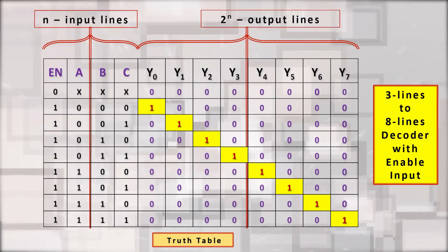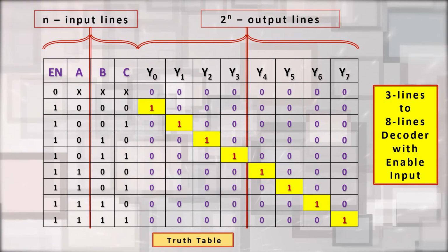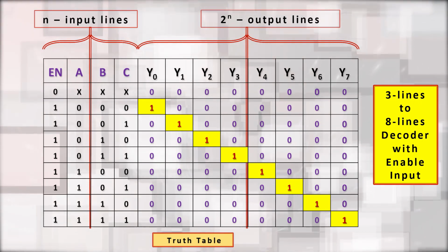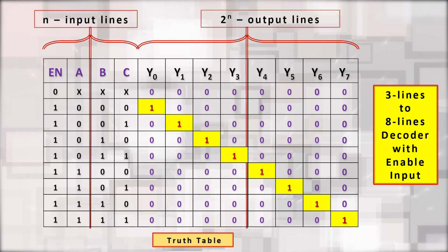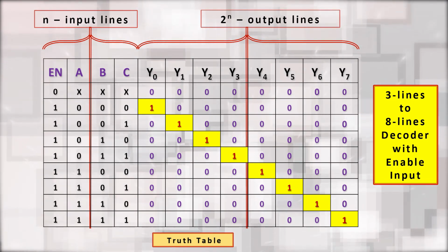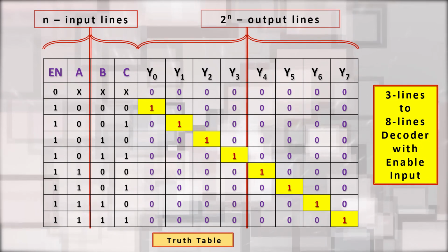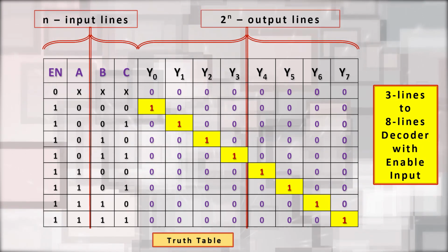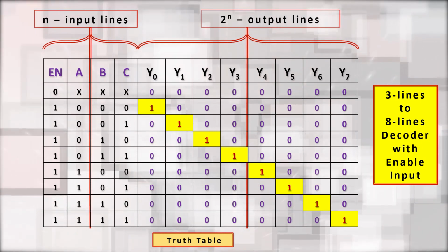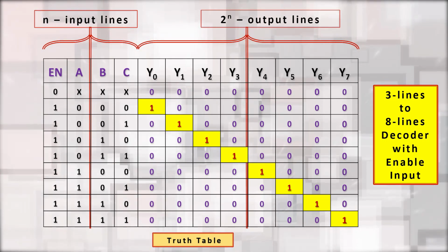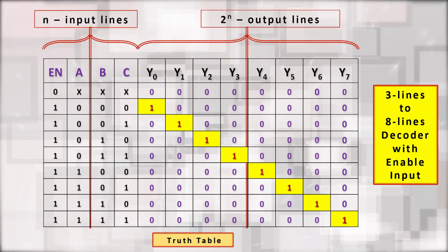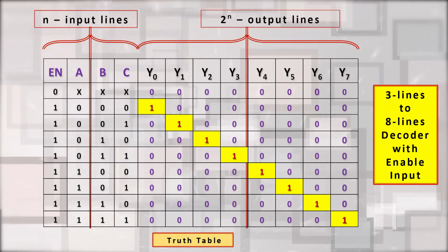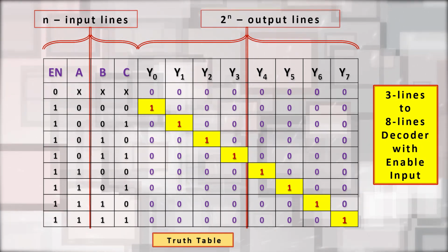In this case, for the 3 bit input, we have one additional input that is called enable. So, accordingly, we can say there are 4 inputs, but when the enable is at logic 0, irrespective of whatever the value of logic A, B, or C, that is, A input, B input and C input are do not care, and no output will be activated.